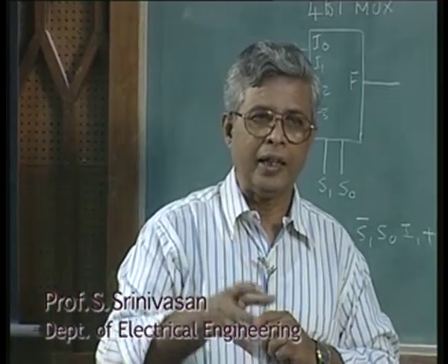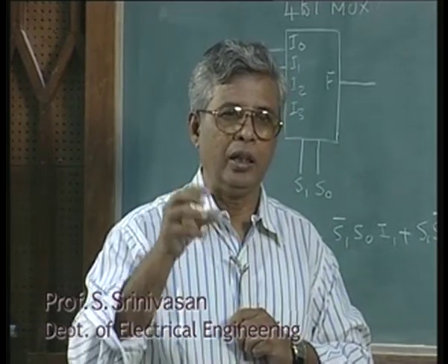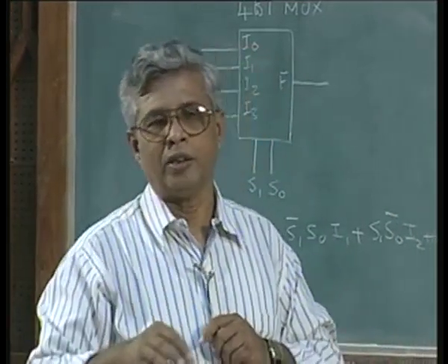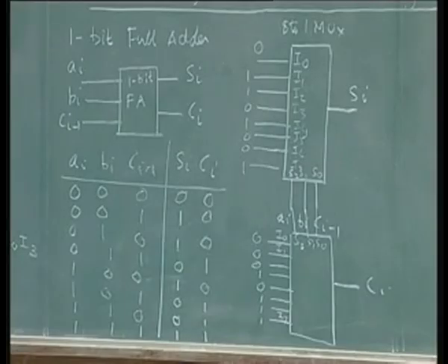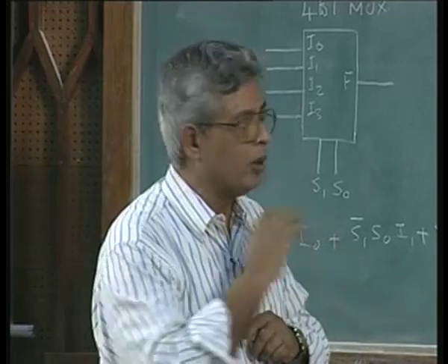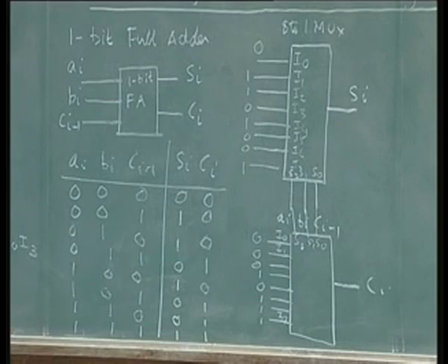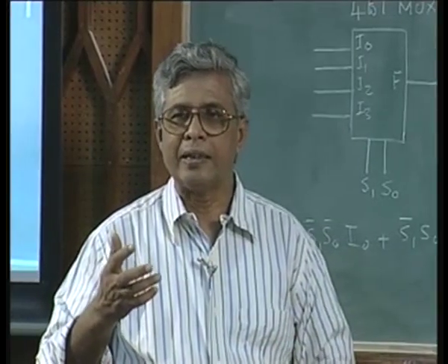That is the essence of IC design, VLSI design. In an integrated circuit design, the essence is to fit into the available or the given hardware as much functional complexity as possible. So, we can optimize it, of course. I am going to show you, this is a waste of 2 8-to-1 multiplexers. This is an approach I want to show you, but this may not be the best way to do it. Can I optimize it? Instead of using 2 8-to-1 multiplexers, which is an overkill for this simple problem, can I do it in a slightly simpler way?